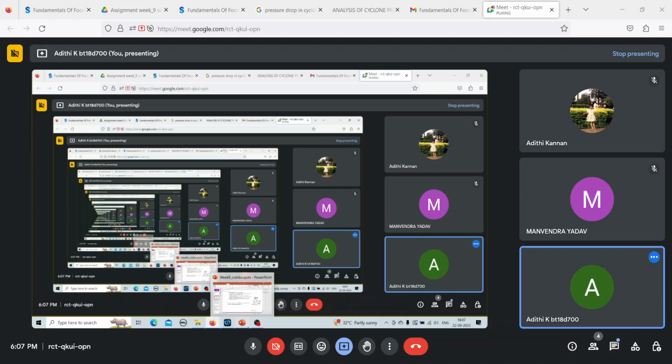So that A corresponds to the third part. Now the centrifugal filters use only the centrifugal force. Cyclone separators use both centrifugal force and gravity once the particles hit the walls, whereas centrifugal filters use only the centrifugal force. Where you feed in your slurry, like how we discussed in the previous slide, through a certain direction and you centrifuge it, the heavier particles will be stuck onto the walls because of the centrifugal force, and lighter particles will remain in the center, and based on that you can separate it out.